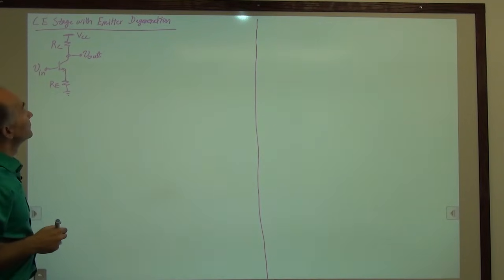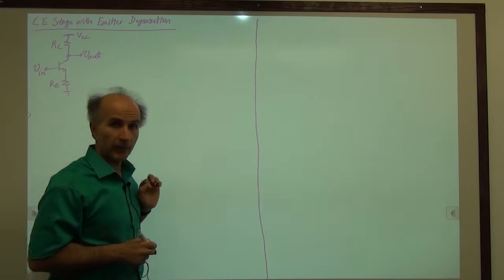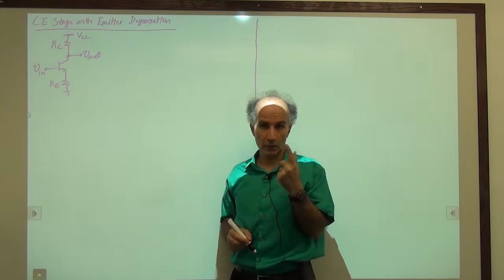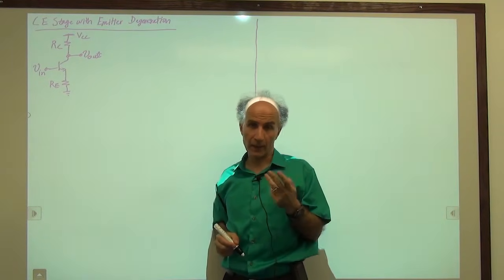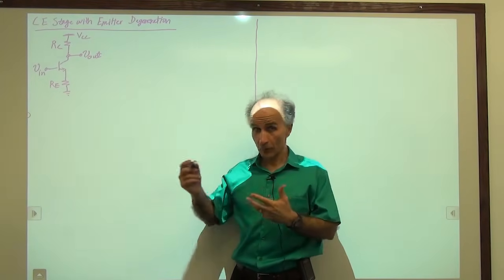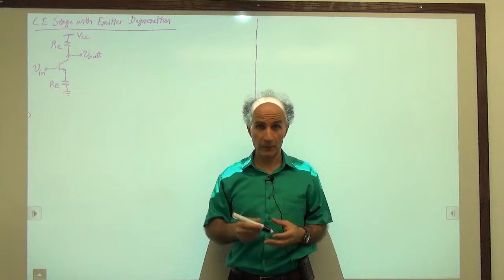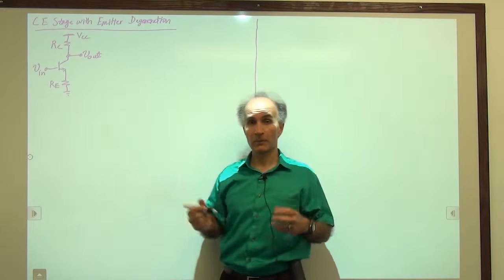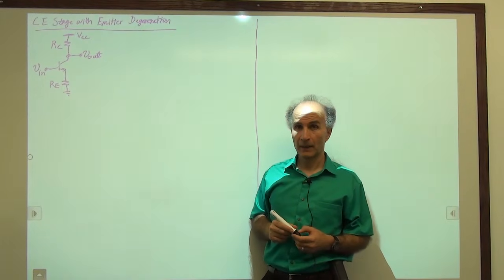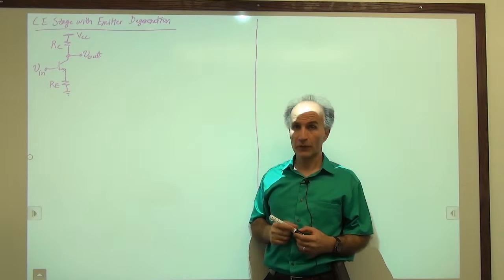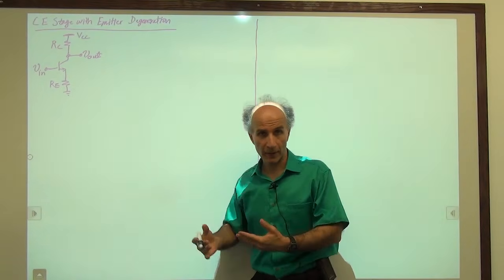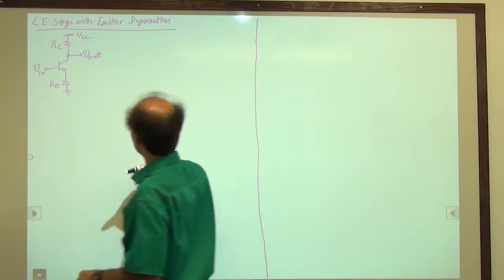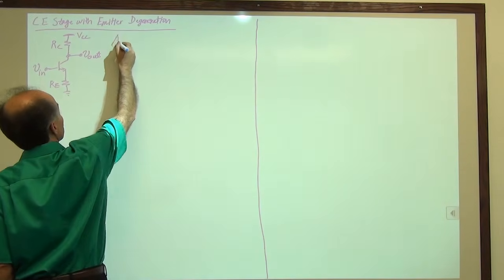All right, so we would like to analyze the circuit. And typically, in cases like this, we are looking for three quantities: the voltage gain, the input impedance, and the output impedance. So this opens up all sorts of interesting problems to solve. One little resistor that we added here suddenly makes the problem much more interesting and much more complex. So we just have to be patient, go through analysis step by step, and make no mistakes. All right, so the first question is, how much is AV?